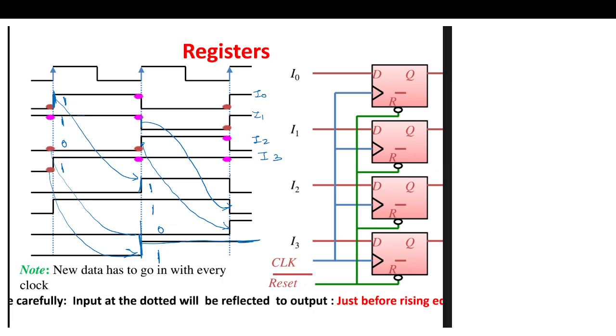At this positive edge of the clock, here we have data. This is also 100. So we have 0, 0, 1 and maintaining it. Okay, so in this way, it is acting like a shift register. At the positive edge, it is shifting 1 bit of data.